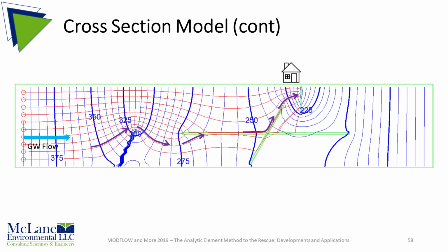When we run the model and trace flow with path lines, we can see that flow is forced upward over the diabase dike, dives again and is drawn into the bedding plane parting zone, and then travels up along the dipping fault zone to the pumping well. This is just a simple example of how one can build geologic features representing fractures and faults into an AEM model to examine vertical flow paths.